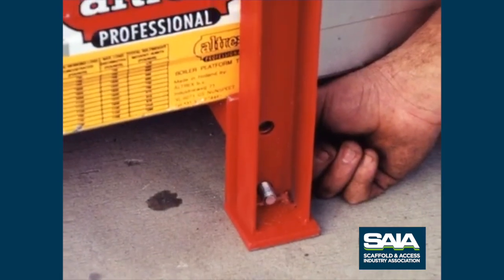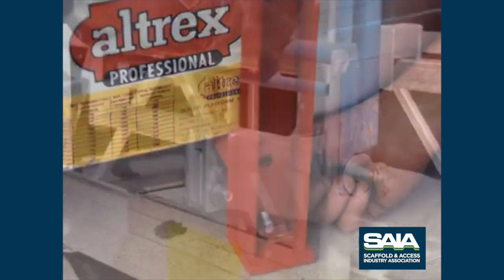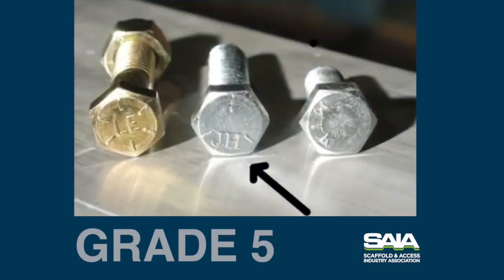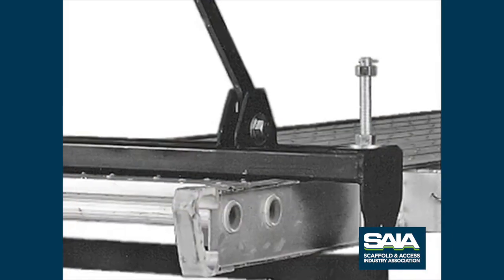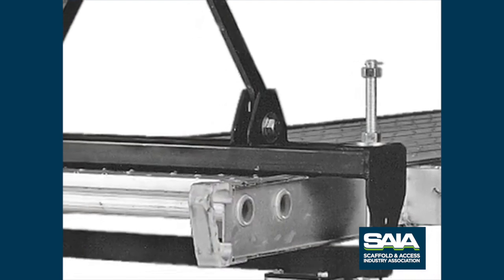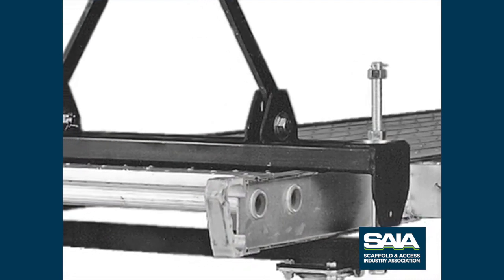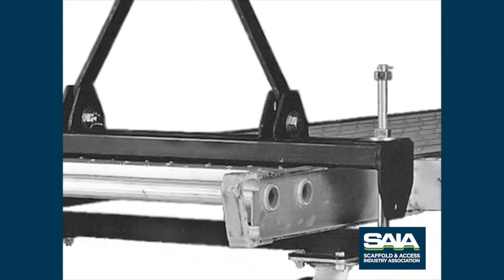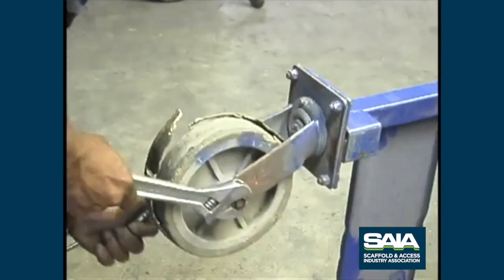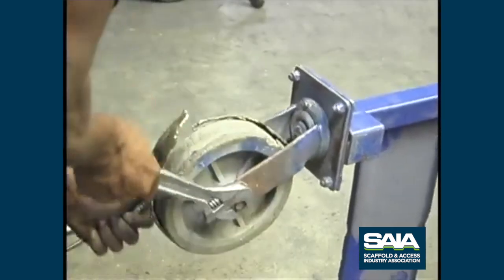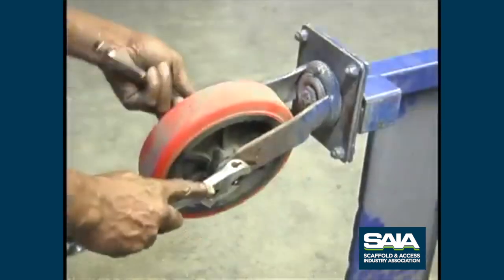Use only the hardware recommended by the hoist manufacturer to attach the hoist to the stirrup. Grade 5 or better bolts are required. Beware of substandard hardware. Use only fabricated platform hold-down bolts provided by the stirrup manufacturer. Do not substitute. Make sure casters and all other components, including tools, are secure.